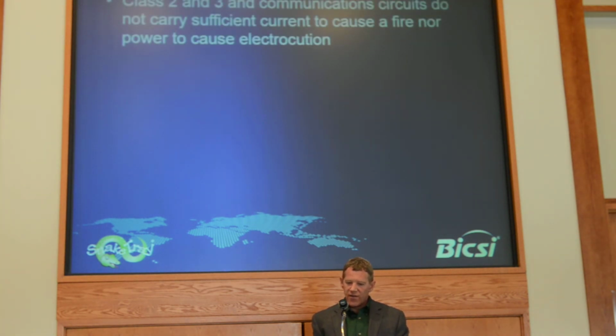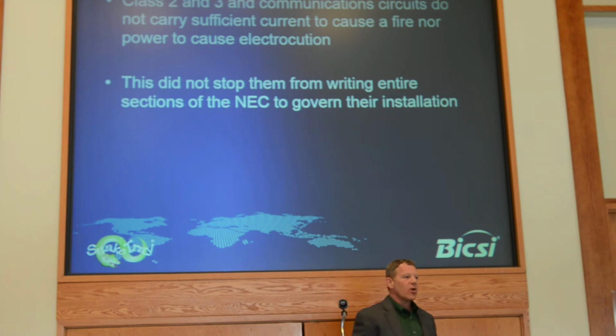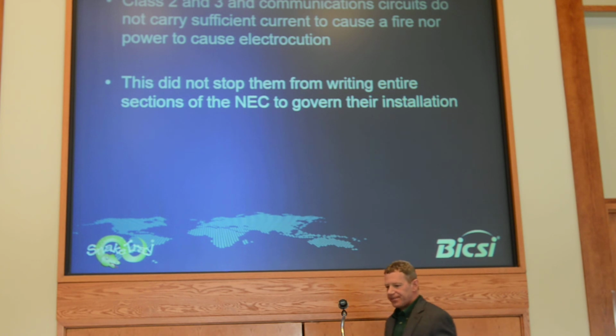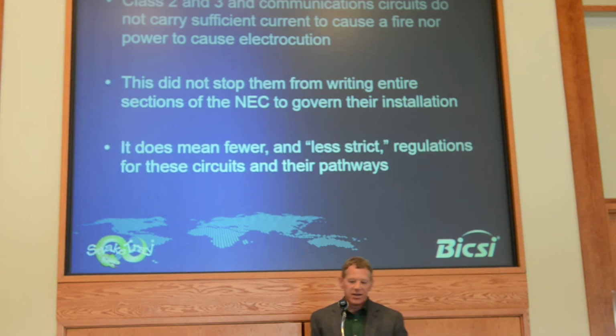Okay, as many of you are low voltage designers, we want to spend some time on low voltage. Class 2 and 3 and communication circuits do not carry sufficient current to cause a fire or power to cause electrocution, but that did not stop the code writers from writing an entire section to cover their use and installation. It does mean that there are fewer and less strict regulations than there are for power circuits.